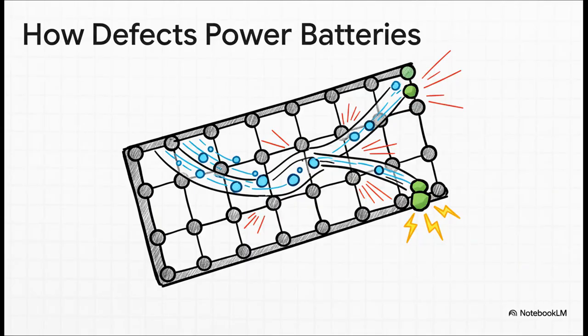So what about that battery question from the beginning? It is all about defects. Those empty atomic spots, the vacancies, they create little ion highways so lithium ions can just zoom through, which gives you fast charging. Dislocations help the material soak up the strain as ions move in and out, preventing cracks. And the impurity atoms we add on purpose, dopants, they fine-tune the whole thing for faster electron flow. We don't just tolerate these flaws, we engineer them in.